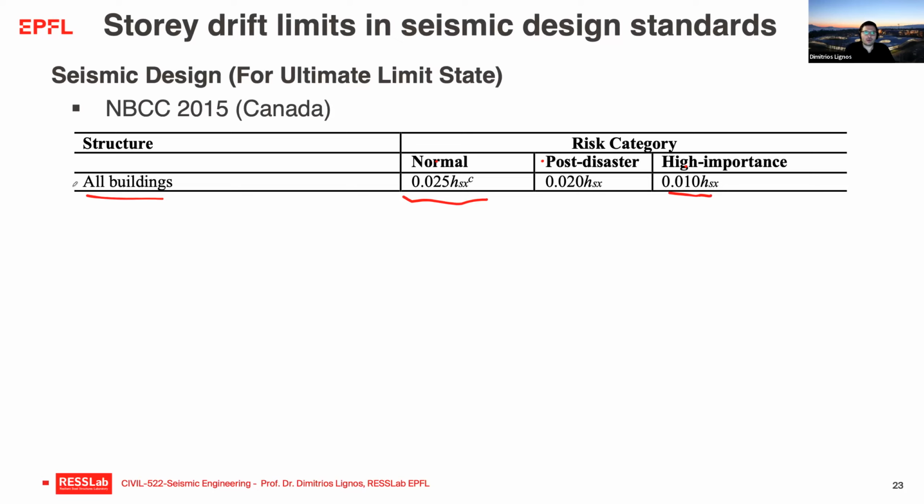height. Notice here that there is no distinction between frame structures, office buildings, wall structures, masonry structures, and obviously, this type of limit would be more reasonable for frame structures that essentially accommodate larger deformations than wall structures.